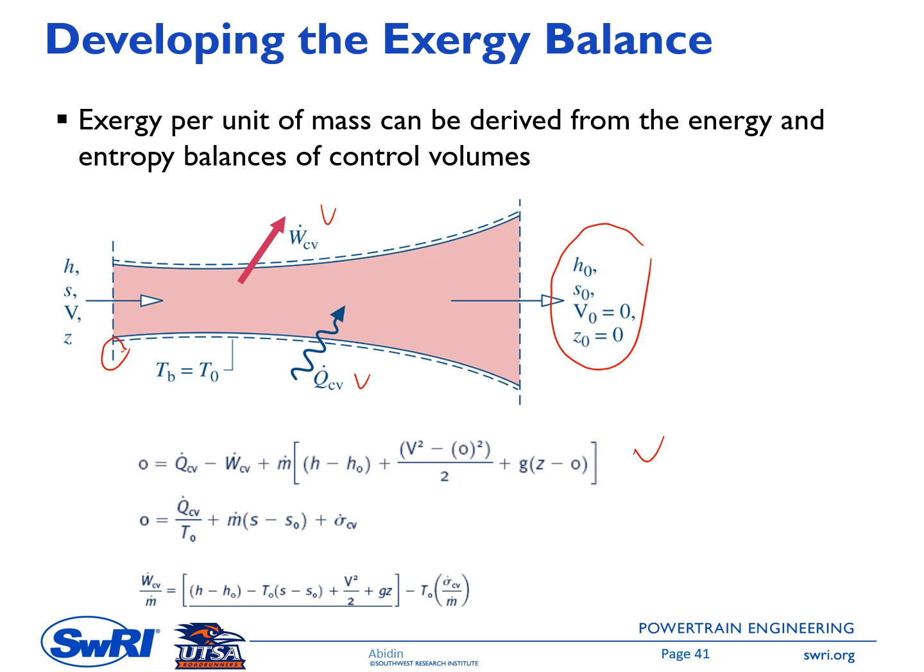And then the next question here is the entropy balance of the open system in chapter 6. Okay, so on the left side it is 0, once again because it's steady state, and then you have Q, you have the entropy flow here, and then you have a sigma here. If you make W explicit, and you replace QCV in the first equation by the second equation, then you will get this one. So this is WCV over m. This is equal to this equation minus this one.